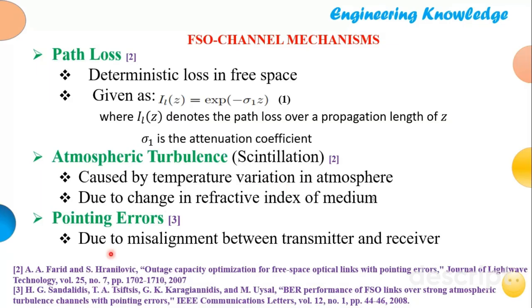There is another context, that of pointing errors. We know that an FSO communication system is a line of sight communication, and therefore the transmitter and receiver must see each other. For that, the pointing error becomes very important, because whenever there is the slightest sway of the transmitter or receiver due to thermal expansion or earthquakes or by any means, the misalignment between transmitter and receiver will lead to pointing errors.